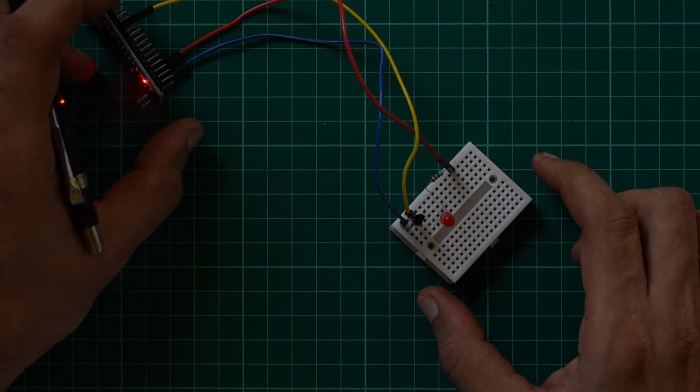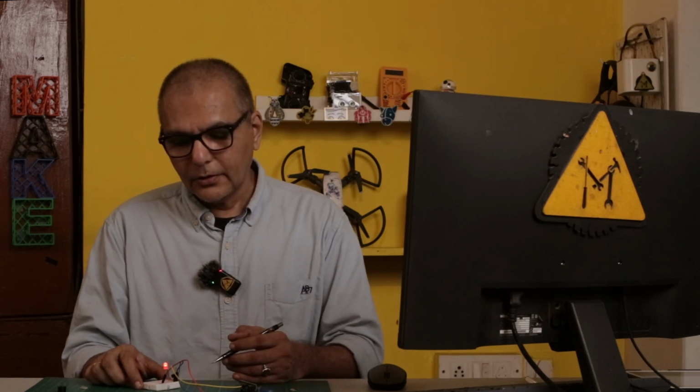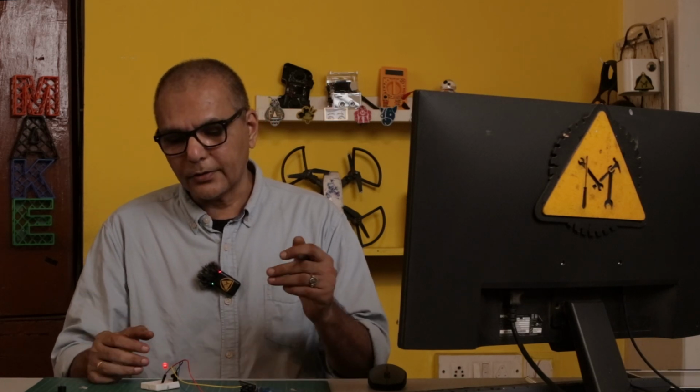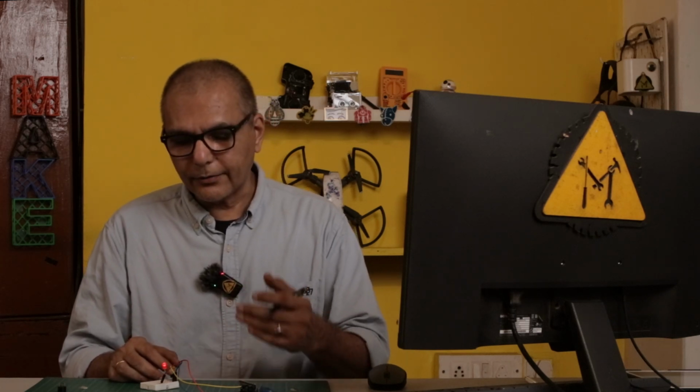So that's a quick look at how to use PWM pins effectively from your Arduino, and also how to couple it with a transistor so that you can drive higher loads. Think of solenoids, or motors in a robot, for example, or turning a valve on and off in an automatic sprinkler system, or any of those applications where you need a device. Think of replacing the LED with something else, and you can run the whole thing using an appropriate transistor. So that's today's talk about how to use PWM and how to combine it with a transistor to drive high power loads, and at the same time adjust the voltage or the current that flows through them.